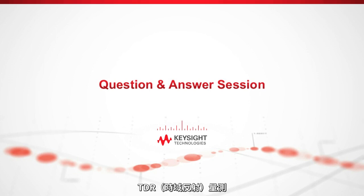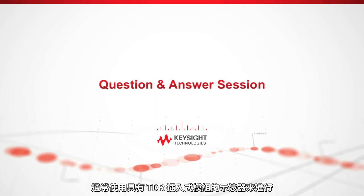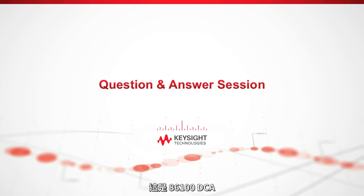Okay, TDR, time domain reflectometry, typically is done with an oscilloscope that has a TDR plugin module. So there was a picture of our digital communications analyzer, which we call the 86100 DCA, and they've got very high quality TDR modules with extremely fast step generators in them. I think they're down to like 9 picoseconds now, which gives you very good time domain resolution. So those instruments, TDR oscilloscopes, can also be controlled with PLTS software, and you can do the same sort of analysis that you can with the VNA. The advantage is that your DCA will also accept optical plug-in modules, so you can get multi-use out of your mainframe instrument.